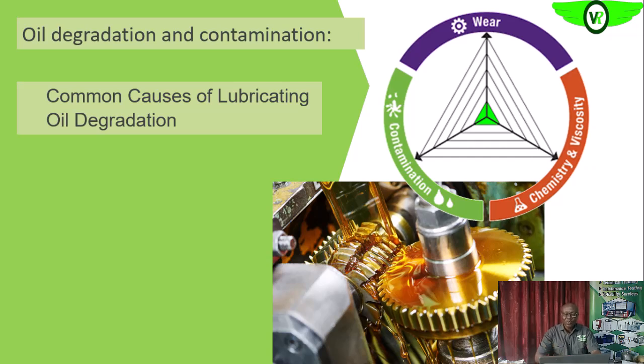So wear particle testing and determination tells us whether the oil is fit for use, or whether the equipment itself is working properly, or some parts are wearing or not.